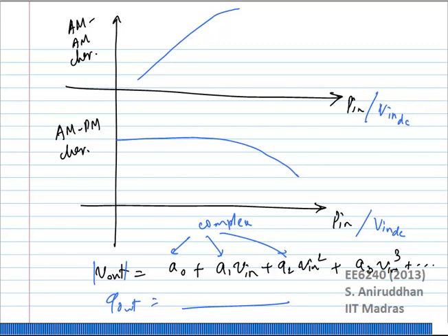So when you actually get this characteristic, you take this guy. Your average power may be here, but you have to characterize it till it clips.